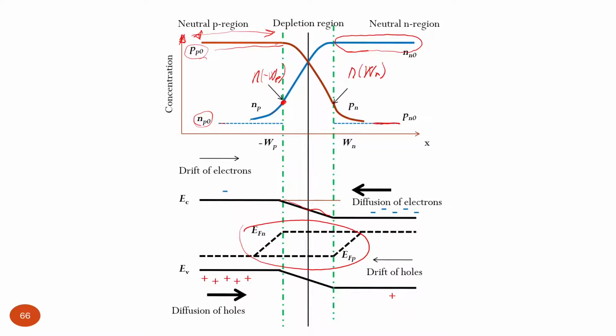So that's why, to be very reliable, we need to operate with the concentration of charge carriers, majority and minority, in the neutral regions, because there we know that there is no strong electric field, and all the changes that happen with the concentration of charge carriers can be clearly described.